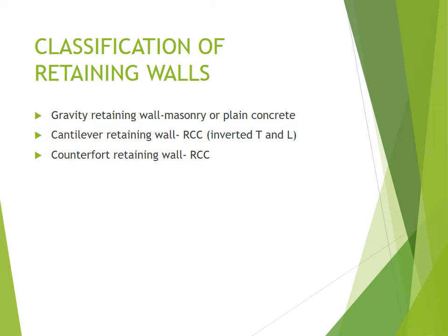Then we look at counterfort retaining walls. As you can see in the drawing, they are either constructed of reinforced or pre-stressed concrete. They are suitable for heights above 4.5 meters. Counterforts are rectangular beams positioned at suitable centers behind the stem and above the base.